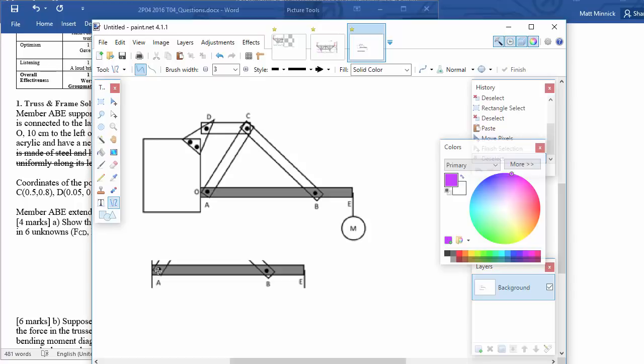it ourselves. So we've got a vector up this way. We've got a vector up that way. On the truss elements, it's going to be collinear with the direction from one pin to the other one, which happens to be just along the truss. Since these truss elements are straight, we've got a weight force going down. And then at A, we've got a force horizontally, not at A, at O. We've got a force to the right, we've got a force up, and then we are going to have a